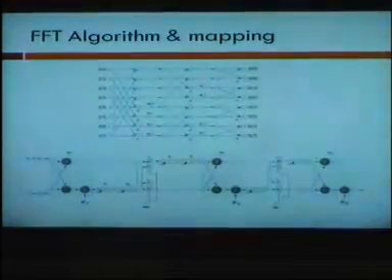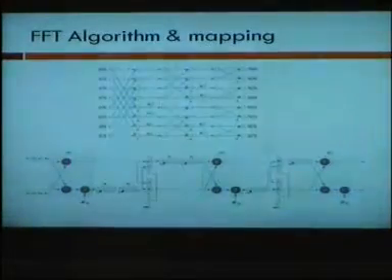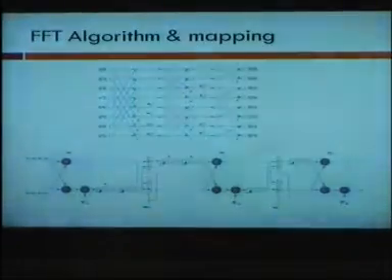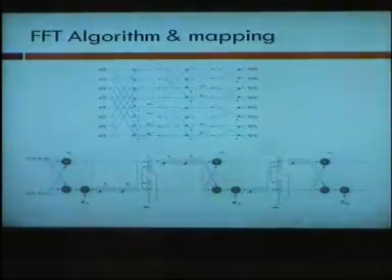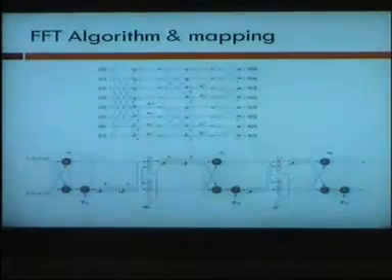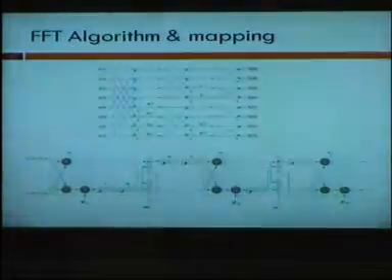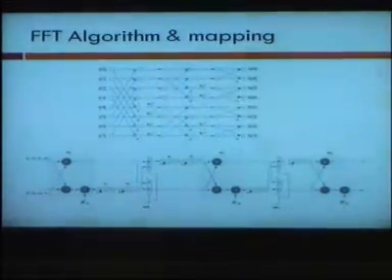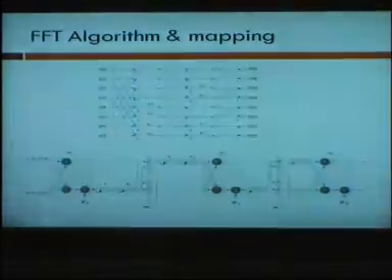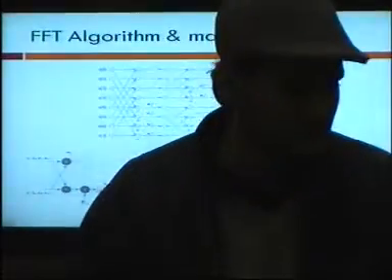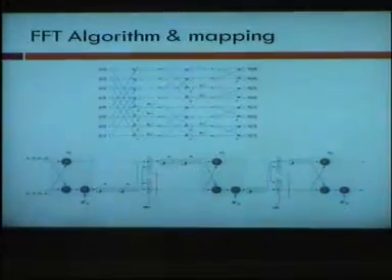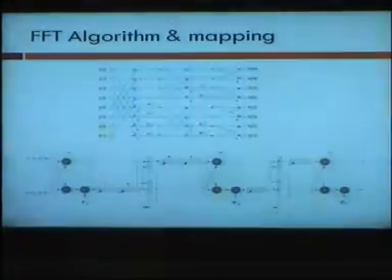Sometimes you say that not an implementation in C but a flow graph will better help you to implement that algorithm in hardware, because a flow graph gives you better visualization of the activities in that algorithm. So sometimes you say, let's draw a flow graph. A flow graph will give you an easy mapping. But a flow graph again is not an architecture. A flow graph is an expression of an algorithm.